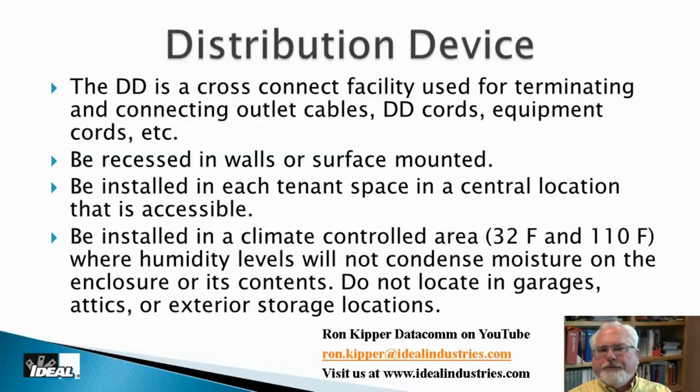Laundry rooms, those kinds of places. Could you not mount this right next to the electrical breaker panel? And the answer to that is yes, you could. Nothing says you can't. It's just not maybe the brightest place to put it because you've got all that electrical wiring that you're going to have to cross to get to your low voltage wiring. So keeping some separation from power is always a good idea. So find a place to mount that darn panel, and then we're going to run wire from it to all the different outlets out there.